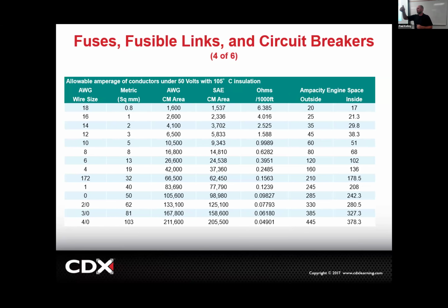you're running the budget up. Now you're running a heavier wire, a more expensive wire. If you have a whole bunch of bigger wires in the car, you know a typical car has several miles worth of wire in that vehicle. If you add all the wires up end to end, it's like a couple miles. If it's a couple miles of this versus a couple miles of this, you're talking hundreds of pounds of difference. Make sense? So they don't want to run overly large wires just in case.